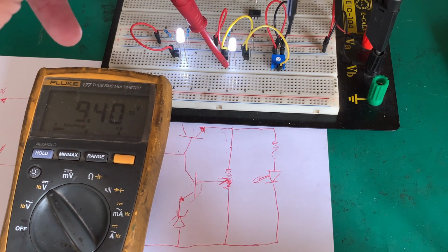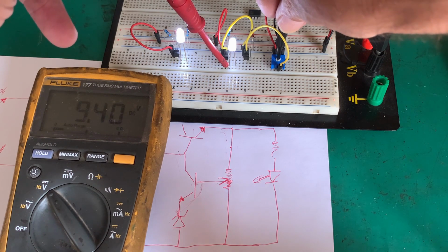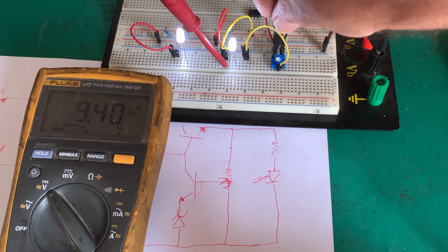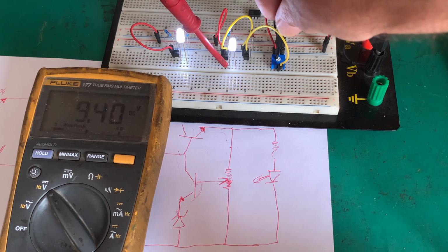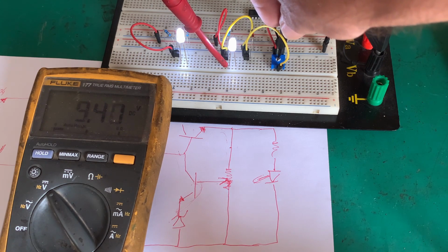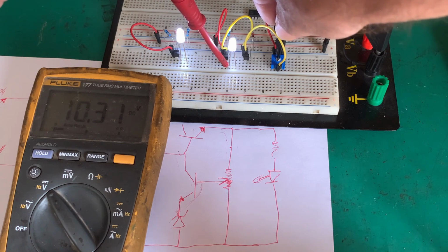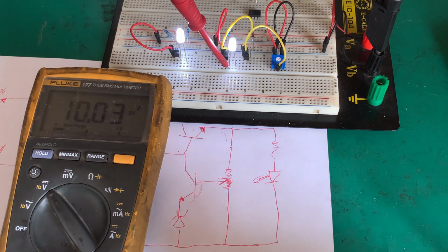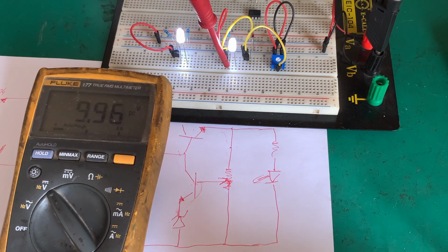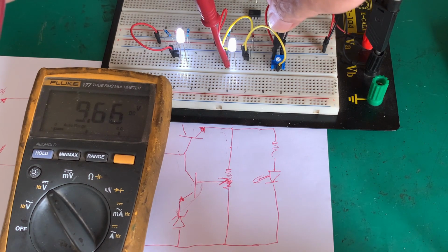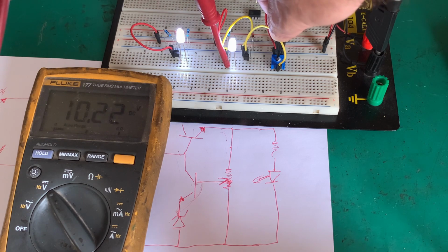And what I'm going to do is adjust this pot. I'm going to add more feedback. If I can get in around this. Oh, just too much. That's good enough for me, for South Africa. So what you can see is by adjusting the pot, I can adjust the amount of feedback to add.